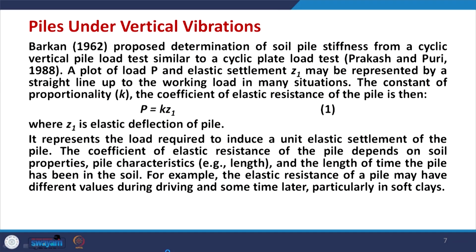When we talk about piles under vertical vibrations, there are many earlier researchers. The earliest one is Barkan in 1962, and you may be aware that Barkan worked a lot on machine foundations. He proposed determination of soil pile stiffness from a cyclic vertical pile load test, similar to a cyclic plate load test, which has been published in Prakash and Puri in 1988.